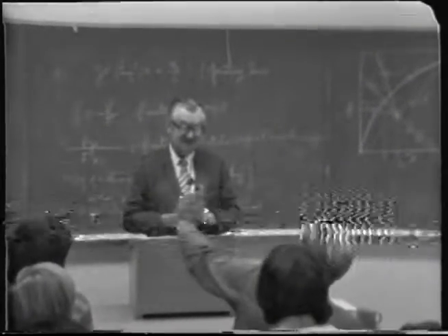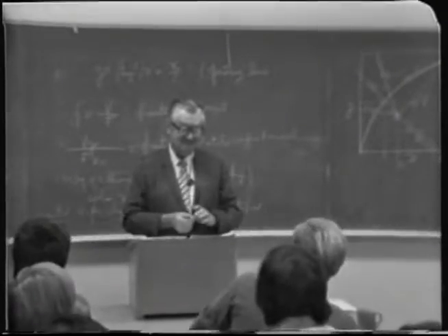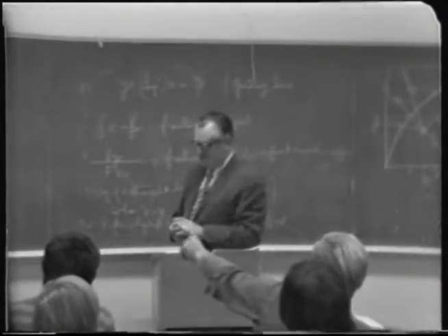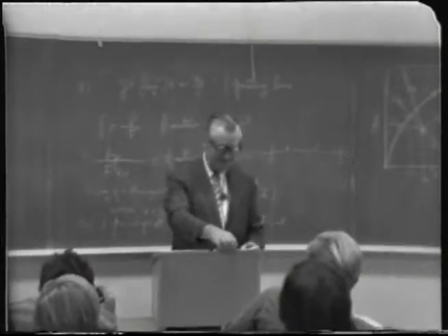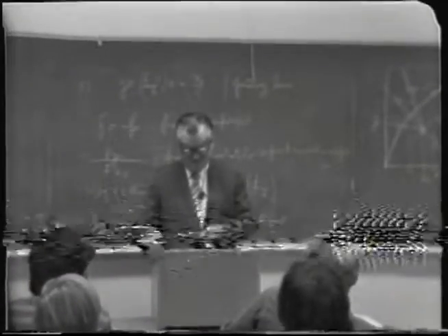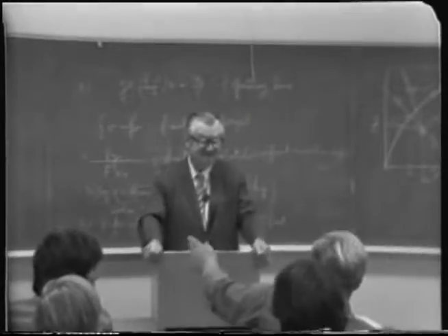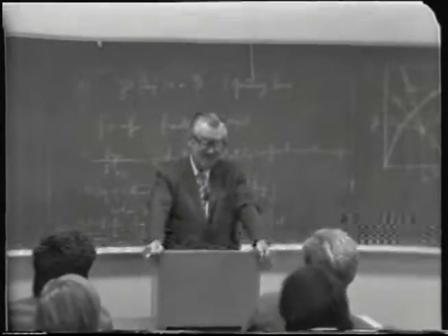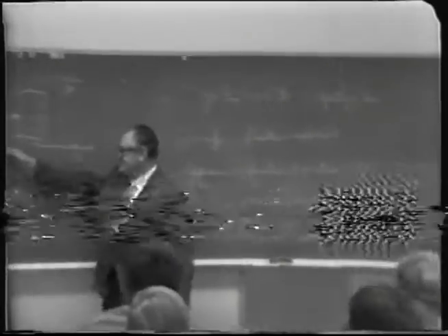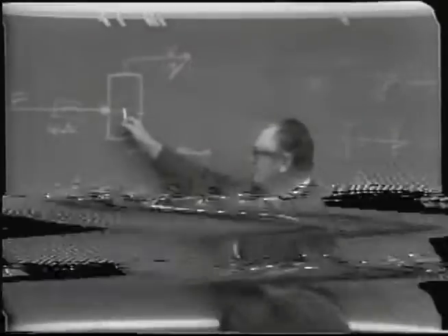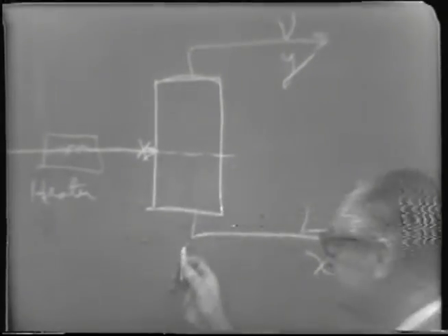The fraction vaporized in the first heater, or inside the distillation? No, we don't allow it to be vaporized in that heater. We keep it under pressure, so it's still in a liquid phase. If there was some vaporization here, we still make the assumption that it's vaporized under equilibrium conditions in here.